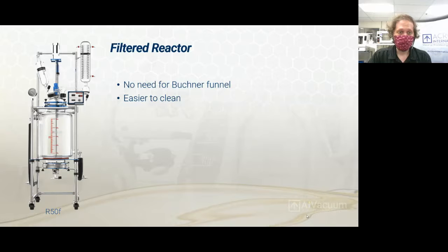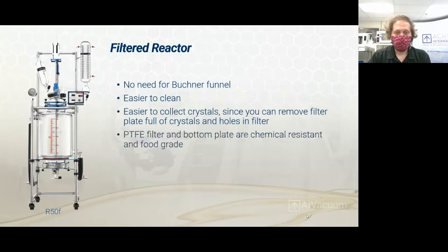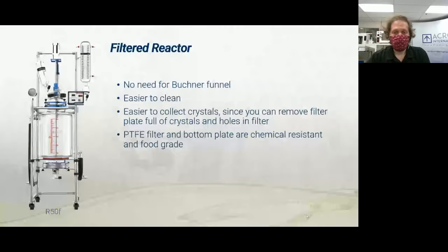Obviously, filter reactors are a little bit easier to clean because you can access the bottom without having to pop up the top. They're easier to collect your crystals or isolates since you can remove the filter plate. That filter plate is PTFE, or on our stainless steel reactors is 316L stainless steel, just like the rest of the wetted parts. And so they are chemical resistant and food and pharmaceutical grade.